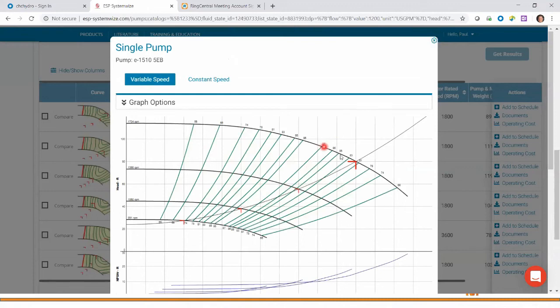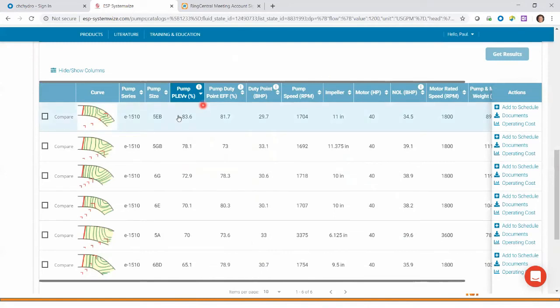We're a little bit to the right of best efficiency point, but as we slow our pump down, we're staying in good efficiency ranges. Now, if this was an open system, NPSH might be a consideration, but at this point, we're assuming a closed-loop hydronic system. Now, what we just looked at was this curve shot here.